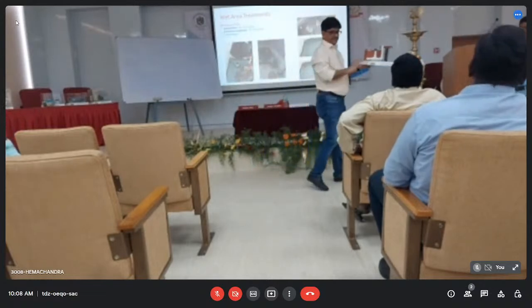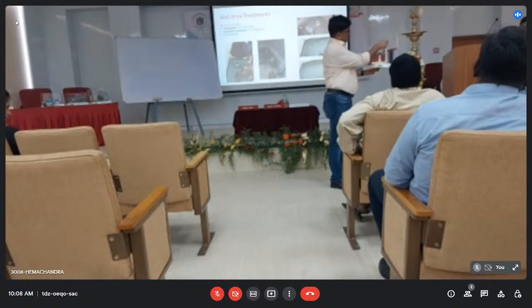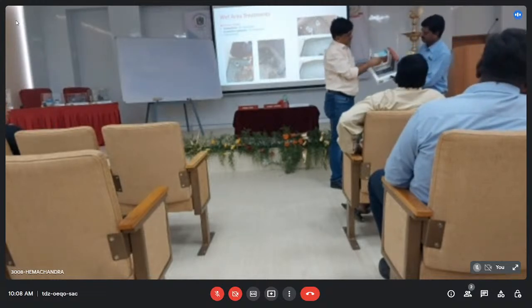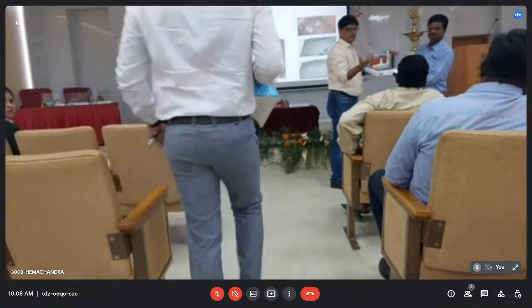You can see this. This is the model. So you can see there is a core cut, right? And then now here the core cut has been done. This is the pipe diameter and how much the core cut has been done. And then after the core cut has been done, this is the tape which has to be put. He will explain about the detail. This is a double-sided tape. Why is it put? Because your PVC never bonds to concrete.